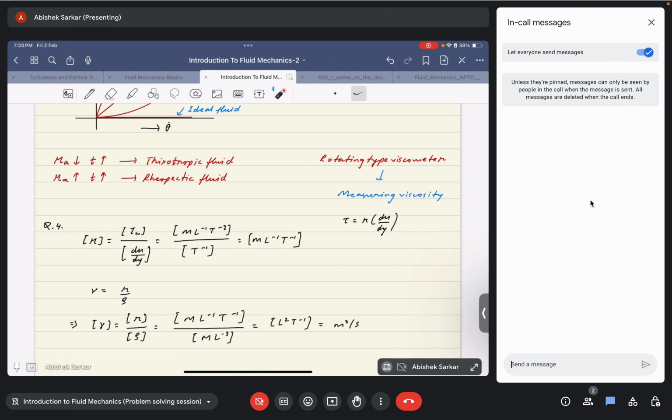The dimensions of the shear stress would be similar to the dimensions of stress or pressure, or force per unit area, basically that. So it will be M L^-1 T^-2 divided by du by dy, whose unit would be T^-1. So the unit of dynamic viscosity would be M L^-1 T^-1. I believe this is a very popular unit that every one of us must remember, that for dynamic viscosity the units are M L^-1 T^-1.